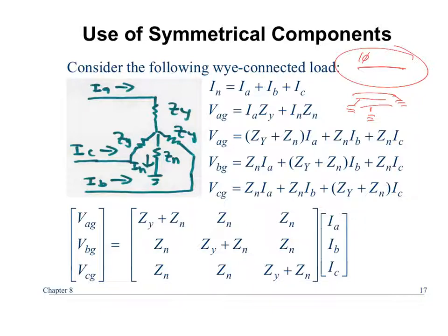So they actually do the brute force approach, which is we're just going to calculate all three systems and go from there. That's why you spend $50,000 and you need fancy software to go ahead and schedule all these things, because when we talk about an 80,000 bus by 80,000 bus Y bus, it's actually 240,000 by 240,000 because you're keeping track of all the phases. So inverting that matrix is not an easy thing.